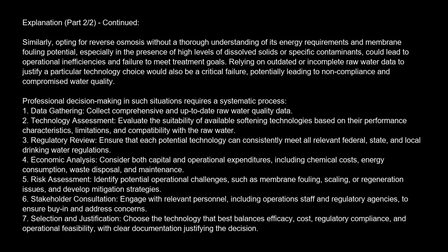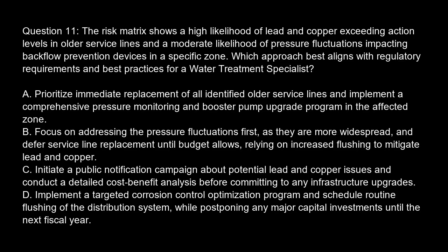7. Selection and justification. Choose the technology that best balances efficacy, cost, regulatory compliance, and operational feasibility, with clear documentation justifying the decision. Question 11. The risk matrix shows a high likelihood of lead and copper exceeding action levels in older service lines and a moderate likelihood of pressure fluctuations impacting backflow prevention devices in a specific zone. Which approach best aligns with regulatory requirements and best practices for a water treatment specialist?